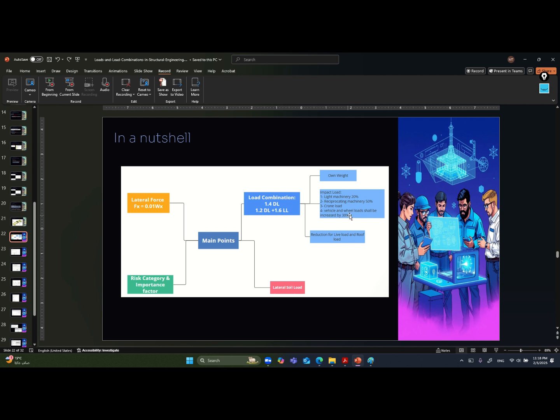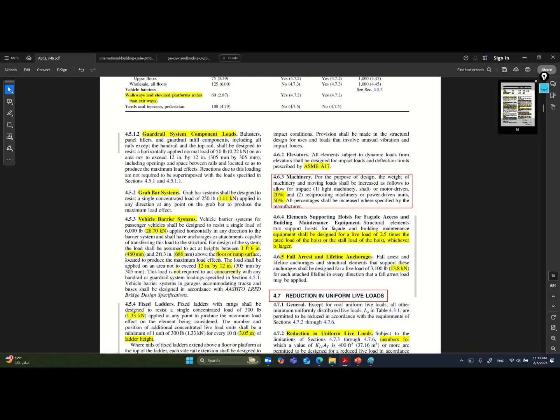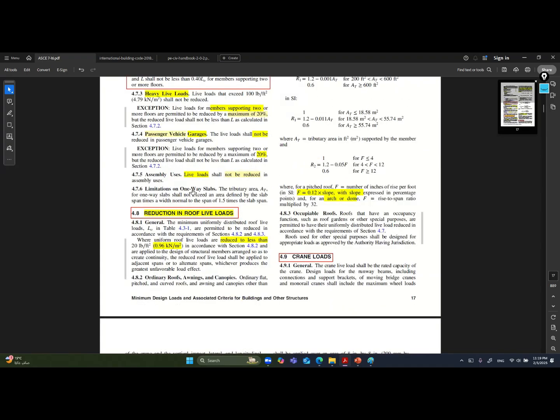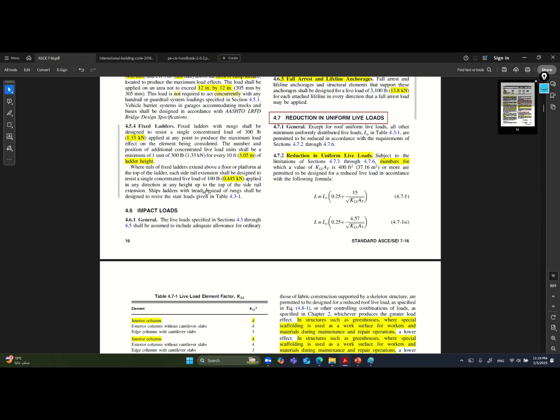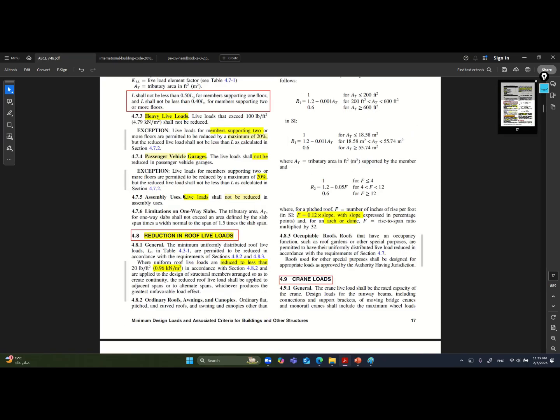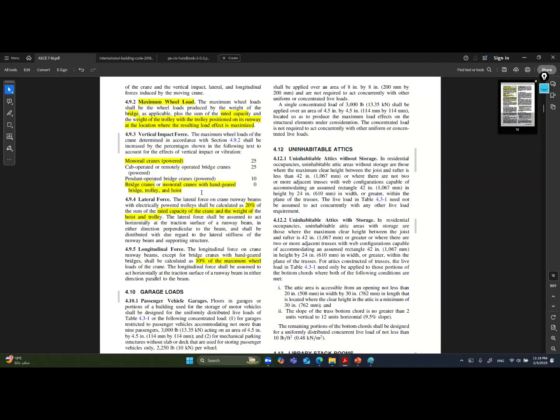Of course, the vehicle and wheel load shall be increased by 30%. Okay, that is a point also mentioned there. Like when vehicles pass through expansion joints or joints in a bridge, then it will be increased by 30%. It is mentioned there, I think, 30%. As I recall, it was mentioned here. But of course, you should go back to ASCE for this one.